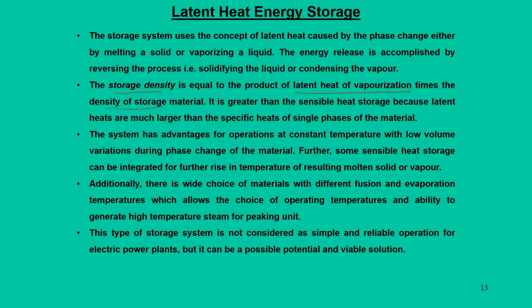Moreover, these latent heat based storage systems are more efficient than conventional sensible heat storage systems, which involve single phase materials, because the heat storage occurs at a single phase only. And we have a wide choice of materials with different fusion and evaporation temperatures. So, this allows a wide range of operating temperature and pressure, and it also has the ability to generate high temperature steam at the peaking turbine.